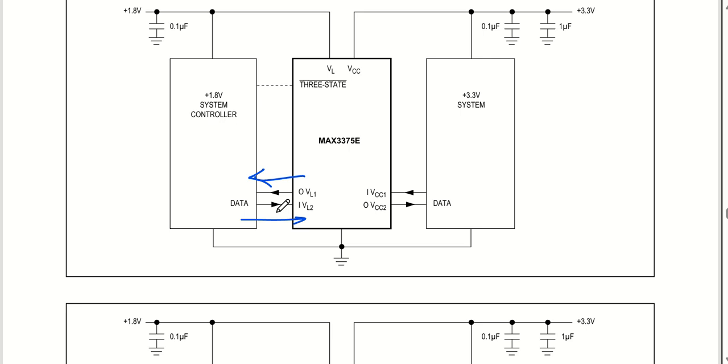Okay. So in that case you can use the 3375 series. One signal will be used as a receiver, one signal will be used as a transmitter. This is a perfect example for your CAN or UART signals. For a CAN signal, one is TX, one is RX, so one line you can use as TX and one line as RX.